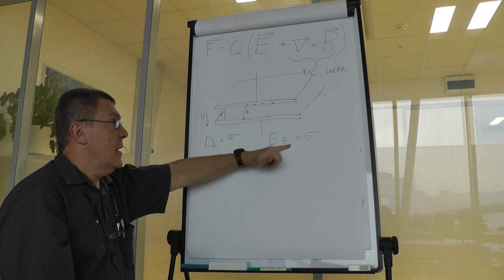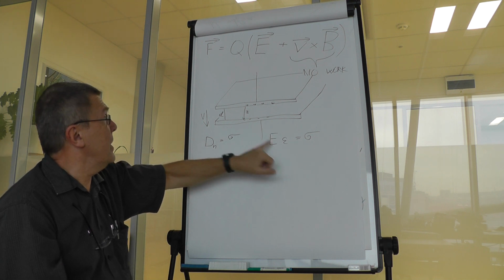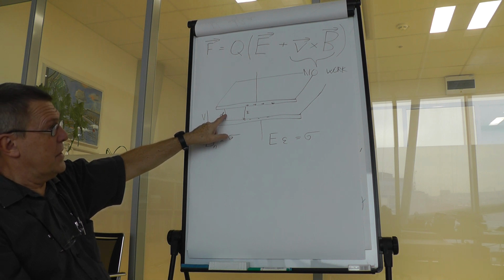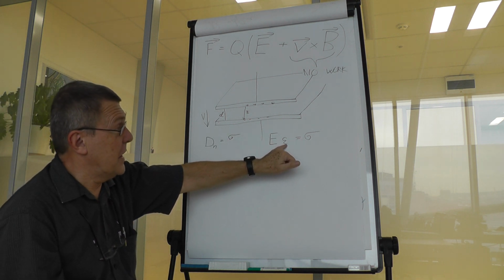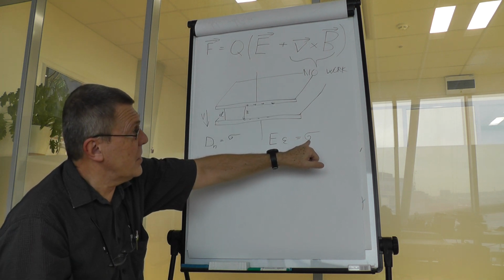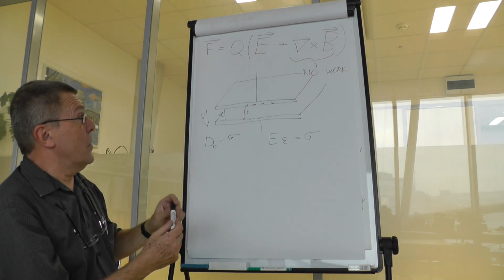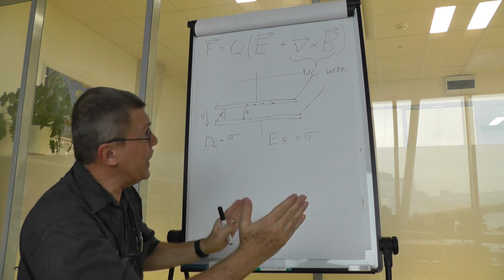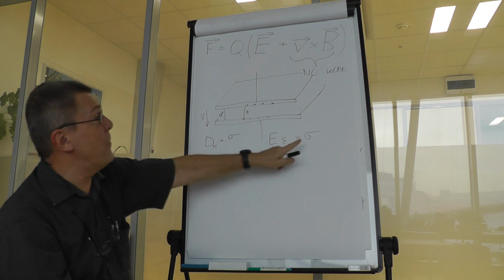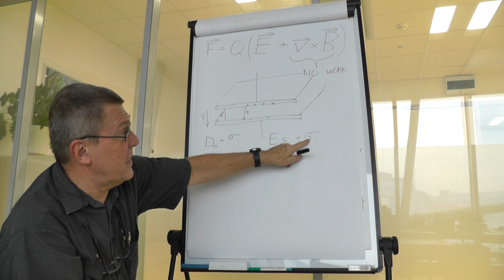Now we know the electric field strength. It is the voltage divided by the distance between electrodes. We know the permittivity, that depends on the material, and we have obtained the charge density. So, for each square meter of the surface, we have a charge of charge density multiplied by 1 square meter.